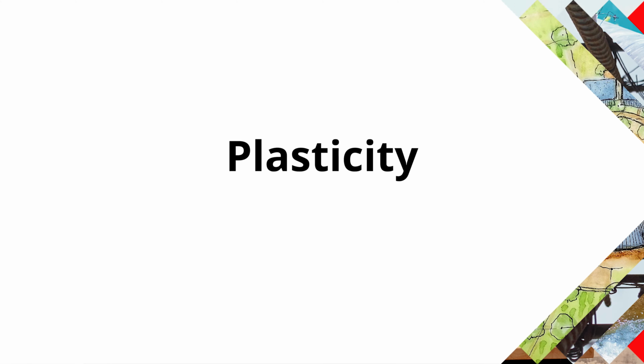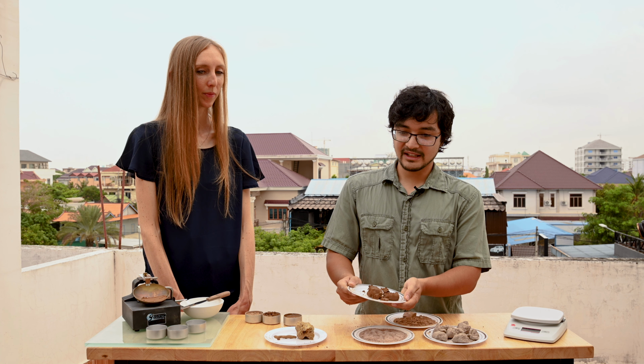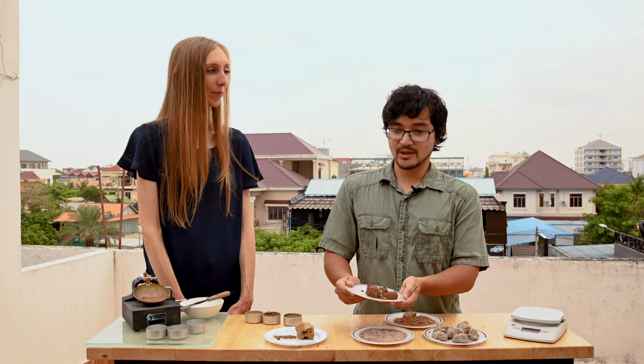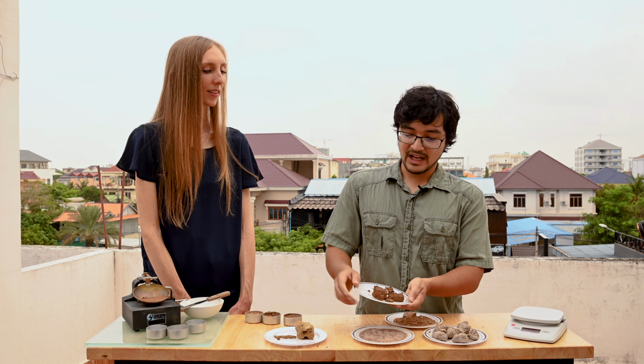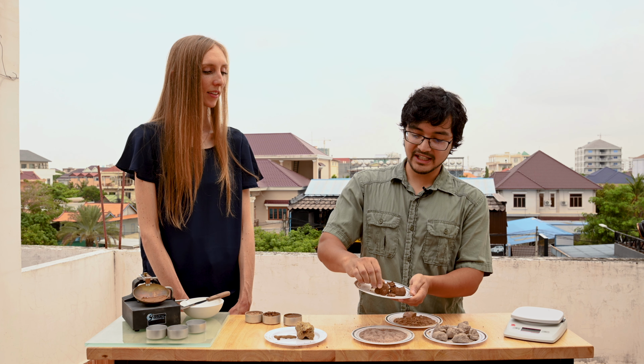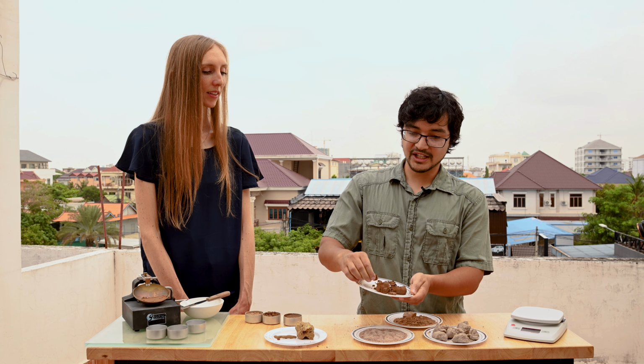For fine-grained soils, you'll also want to comment on the soil plasticity. Plasticity is the ability of the soil to undergo deformation when applied stress. For coarse-grained soils, for sands and gravels, when you apply a force, the particles separate, but with clays and silts, as you apply a force, they actually can squeeze and stretch.